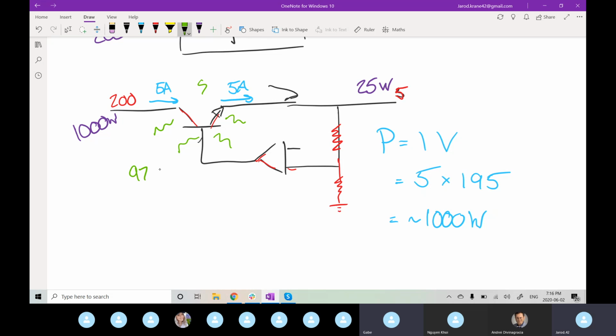So that's the downside to linear regulators. The more current you're passing through, the more energy you're losing because of this current in, current out rule. And that little transistor bears the brunt of all of this power loss, so it gets really hot and the resistance goes up. So these linear regulators and LDOs are not meant for high current supplies because they're going to get rid of all your energy and overheat, which is why people invented the DC-DC, which Jared will talk about next week.